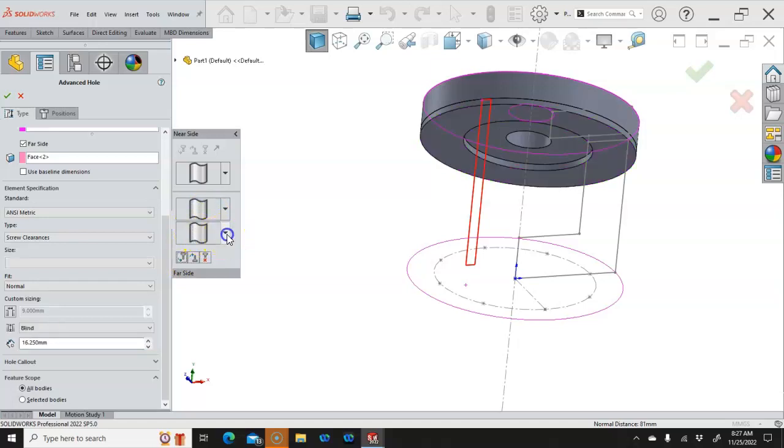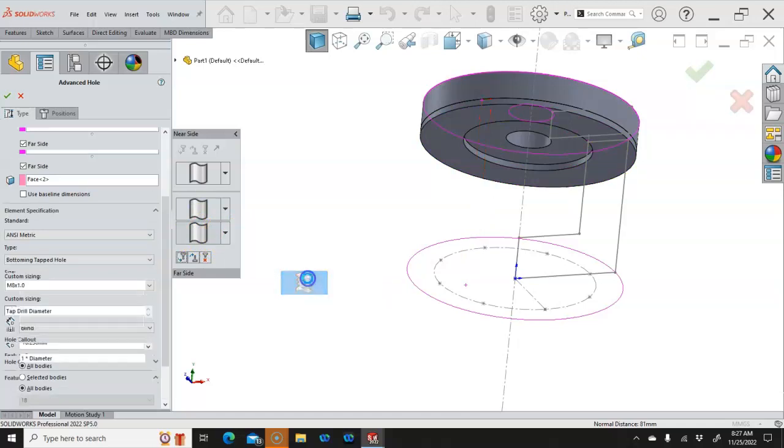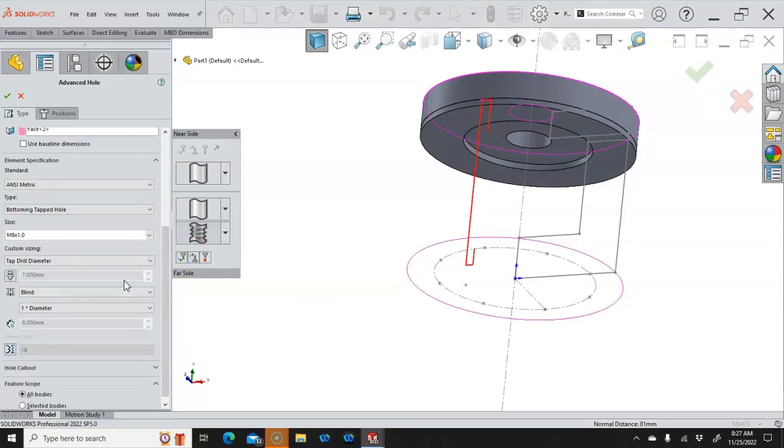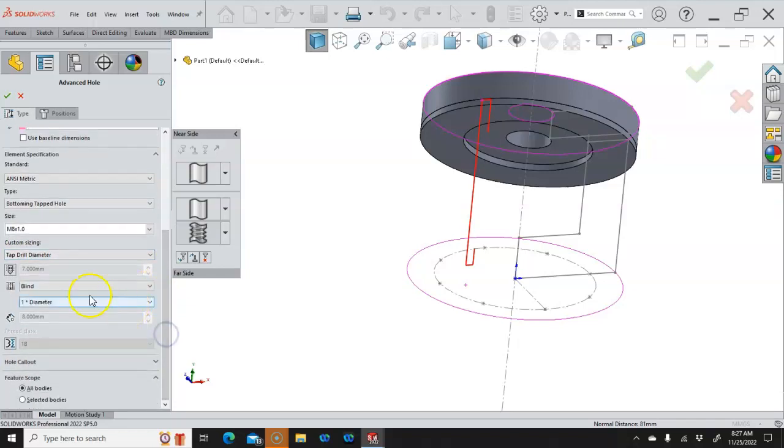Okay, insert, and then we're going to go with the straight tap, and that one's going to be a blind in condition. We said we were going to go about 25 on the depth. All right, so it's blind in condition 1 passed.